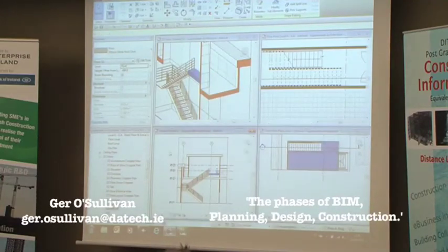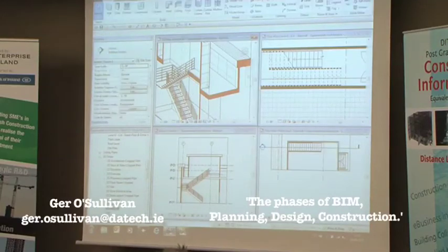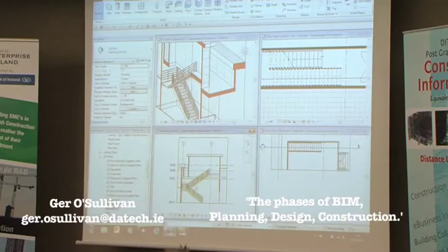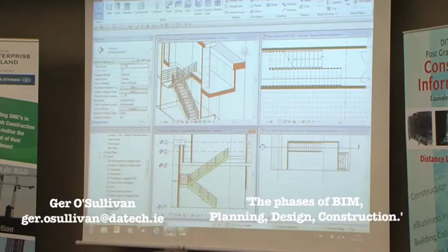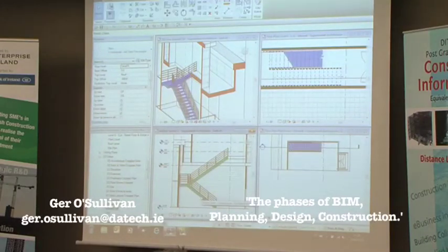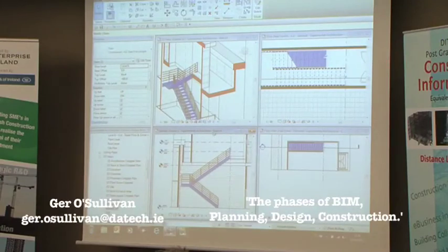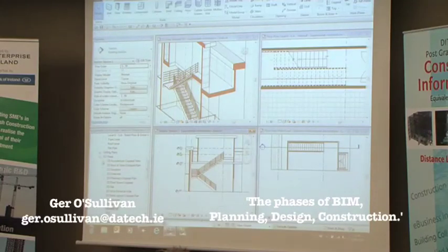But again, we're not finished, but because I'm in a kind of 3D environment, I'm seeing it from all angles, I can pretty much see here in my section that I do not have enough headroom from here. So that's where the floor is back here, and I can just measure, and you can see it's only about 1800. So we need to move the stairs. Again, we can just nudge it by eye. But what I want you to see is, up in this view here, you will see that the floor is now moving with it, so I don't have to worry about the opening anymore. It will actually move with the stair because I locked it in. So I know these are small features, but again, it's all about time saving. It's all about putting in intelligent information in the first place that you can then edit very, very easily. So that's just another feature.